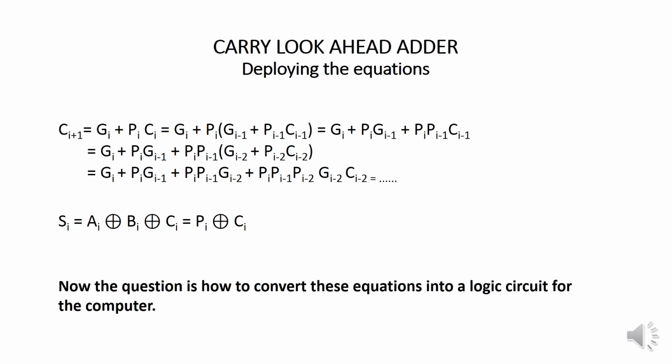Let's first concentrate on the second step, the one using the combined equation. For this, if I unroll the recurrent relations for the carry and for the sum, I have this unroll equation, where I have substituted successively the values with their corresponding combined equation.